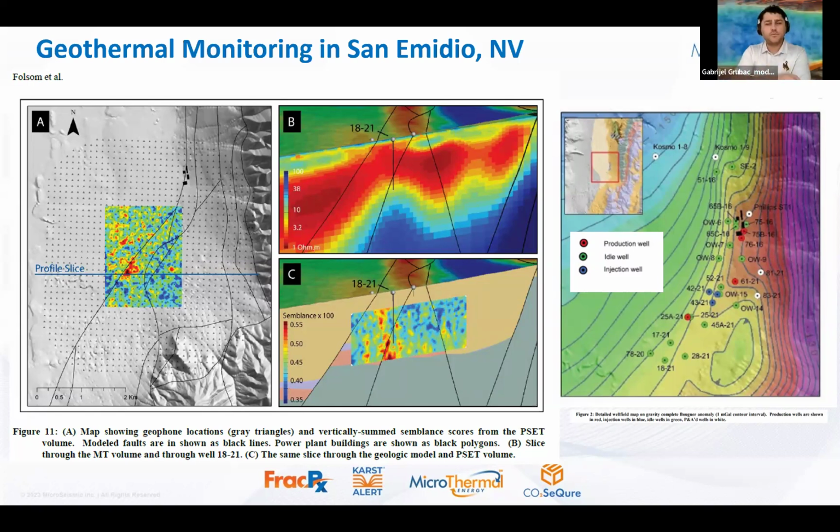But on that same note, Jonathan, if we're thinking about secondary leak off systems, right? Let's say you're in a natural fracture system, and you're generating a main fracture, but you're leaking off into the secondary system. Is this where your workflow and the DFN comes into play? Like, how do you work with the uncertainty analysis on that in terms of fluid distribution and essentially proppant slurry dehydration as you're dealing with the fluid loss and distribution?